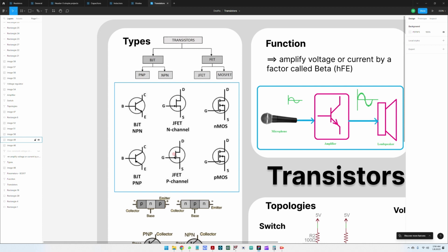The JFET transistors are usually used in some of the best high impedance applications. So let me give you an example for EKG signals, which are connected to the body. Usually they are used for high precision amplifiers. The JFET transistors are used for instrumentation amplifiers. So very high precision equipment uses JFET transistors as an input type of transistor.